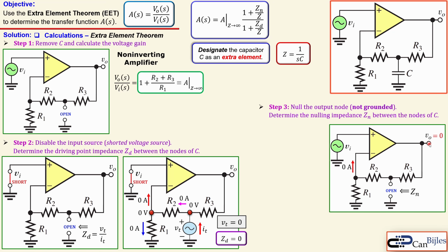We have here 0 volts, and this is looking now here in this direction. You have actually here a connection which is a series combination of R1 and R2, and you have on the right side a resistor R3 which is going to the 0 potential, which is exactly the same as ground in this case.